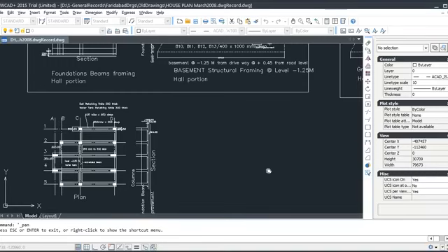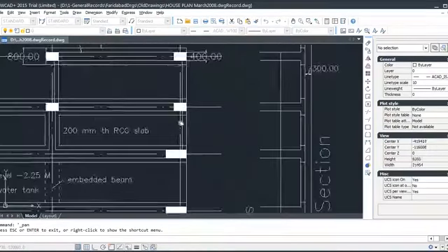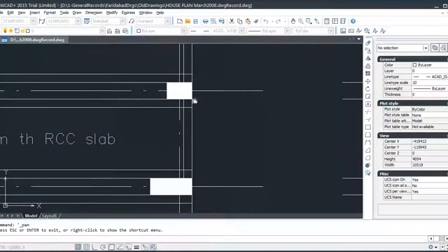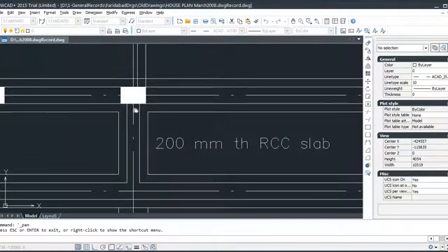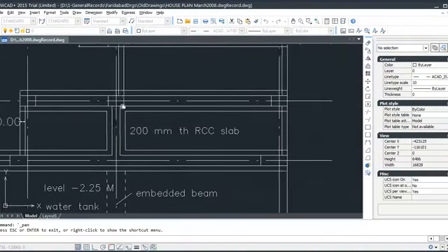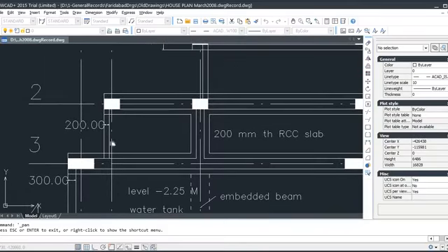So we use ply and timber for that. We did not use your standard columns of contractors. These columns are 40 by 60. You can see here this column is 40 by 60, or you can say 400 by 600 mm, because this is quite more than 6 meters span. The same thing is here, 400 by 600, 400 by 600.